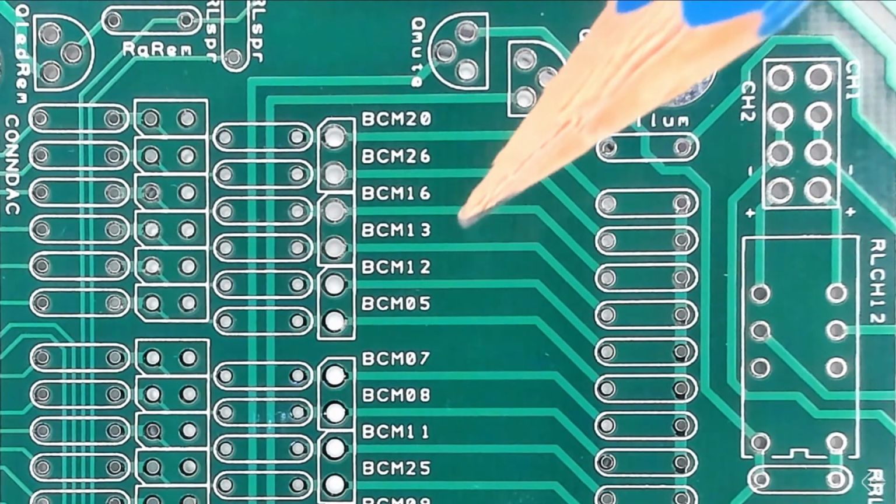So as far as these traces are concerned, just to keep the numbers simple and easy to design, I don't know what these ones in particular are, but the board that we're going to make, we're going to keep the traces at 0.2 millimeters, unless we need to push a lot of current. And when we need to push more current, we're going to increase the size of that trace. Now, how much do we increase it by? Actually, it's not that difficult.